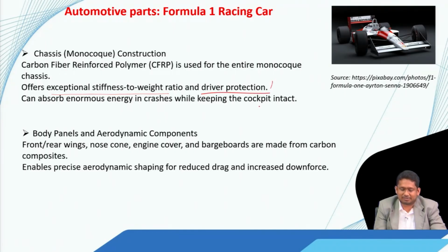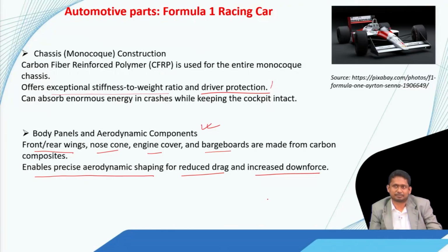It better ensures driver protection. Body panels and aerodynamic components are also made from composites: front and rear wings, nose cone, engine cover. Barge boards are made from CFRP. It enables precise aerodynamic shaping for reducing drag and increasing downforce.